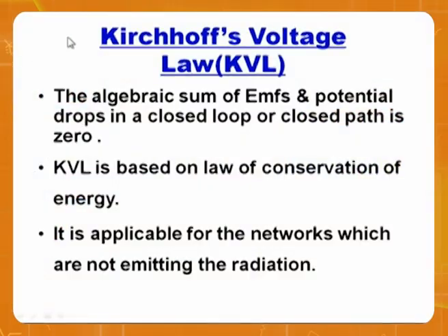One is KVL and KCL. You see the correct spelling, Kirchhoff's voltage law. We call it by the abbreviation KVL. What is the law? The law is basically telling that the algebraic sum of EMFs and potential drops in a closed loop or closed path is 0. Why do I use this word closed loop or closed path? When there is a capacitor, the capacitor is really an open circuit.